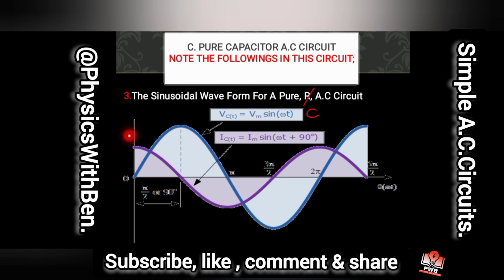The current reaches its maximum here before the voltage is reaching its maximum. This is it. The current reaches its zero value here before the voltage is reaching its zero value here. And so in each, the current is arriving at that place before the voltage. So the voltage is lagging by 90 degrees or pi over 2.